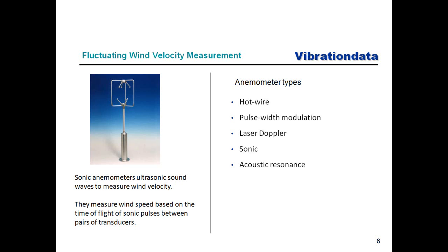And this is based on the wind speed as the ultrasonic pulses travel from one transducer to the next. So that's all mapped out, and depending on the wind speed, that will distort the travel path, for example, and will cause a phase change or a change in the timing, which can then be related to the wind velocity that's causing that phase delay or distortion to occur.